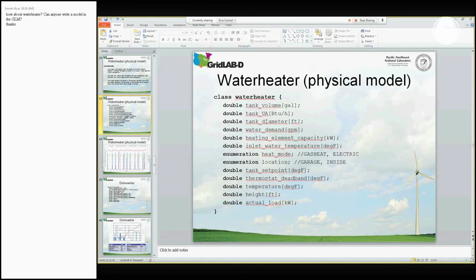So you can just go to, for example, Lowe's.com and look up your nearest friendly hot water heater, and most of these values are specified. If you don't know it, then there's good defaults built in here. So, for example, inlet water temperature defaults to, I think, 58 degrees or something along those lines, which is pretty common for the average of most groundwater, if you look at the average throughout the course of the year.